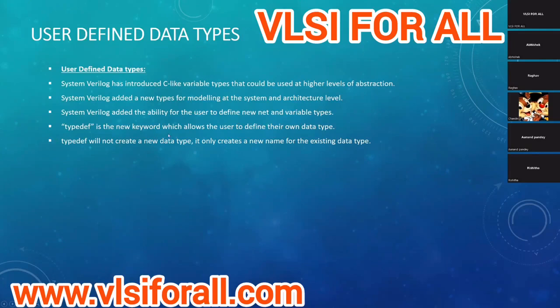Using typedef will allow users to create their own data type, and this is basically not creating a new data type. It's just renaming an existing data type. It can be a primitive data type, like you can rename an integer to your own name, or you can create a complex data type, for example an array. You can rename an array of bit, 8-bit wide packed and 256 unpacked, as memory one, and then you can create an array of memories. So you can use typedef for that purpose also.